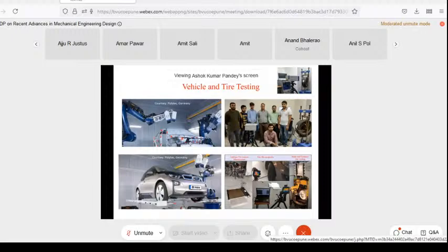For example, let us say you have a vehicle design, and this is more or less the first frequency mode of this whole car body. Now when you put the door on, there may be another frequency which comes over here, right? When you put the wheel on, another frequency may come over here, right? As you add the mirror and all that, there are many more components in the vehicle, and you'll see that they will have different frequencies.